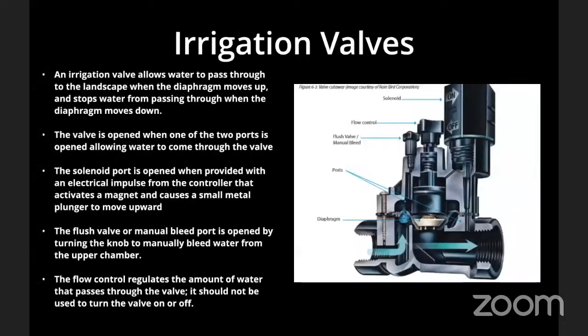Okay, so drip irrigation system components. If you have an automatic system where it's connected to an irrigation controller, it starts at the valve. Now, you can set up a lot of this architecture in a way where you can adapt it to a hose if you need to. I'll show some pictures about that later. But ideally, in most situations, it's connected to a sprinkler valve.